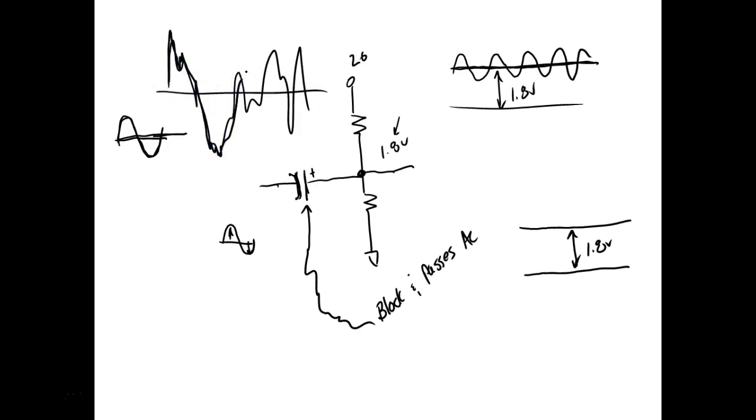What we've got on sound is all these different frequencies superimposed on top of each other, but your positive is still going to be a mirror image of your negative, right? You understand? And your DC meter is going to average this out. So we can check our bias even if the amplifier is active.